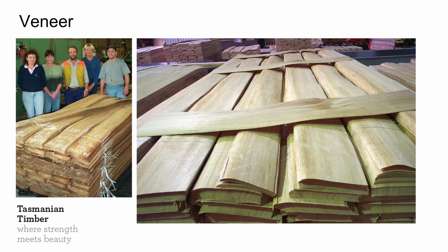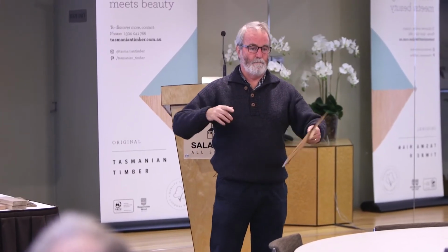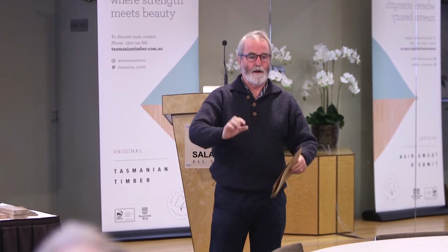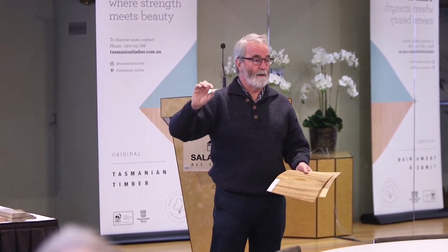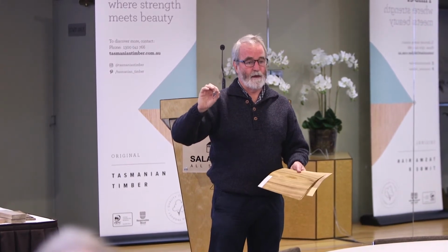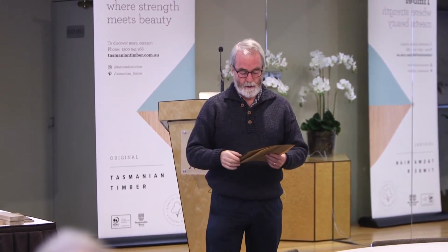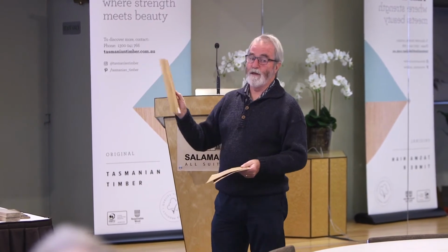So if we're making plywood, we're going to take the log and we're going to peel it. So put it on a big spindle, we put a blade on it, and it all comes out as a strip. It's usually 2.5 to 3.5 millimetres thick, depending on who's making it and what you want to make it into. This sort of veneer is appearance veneer.